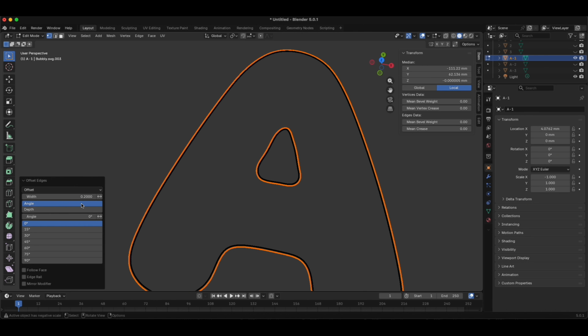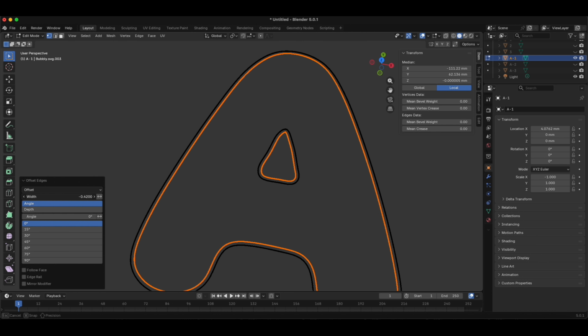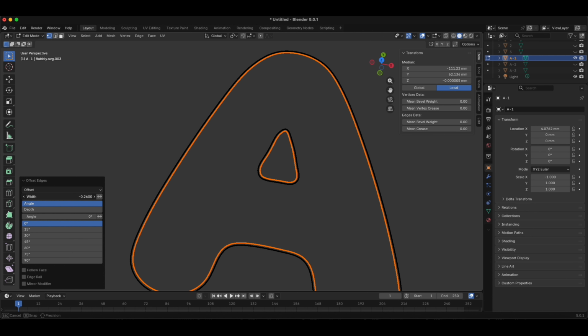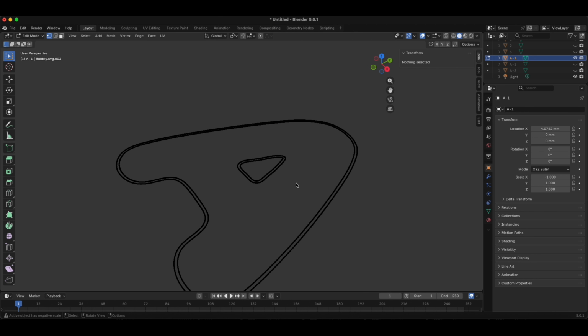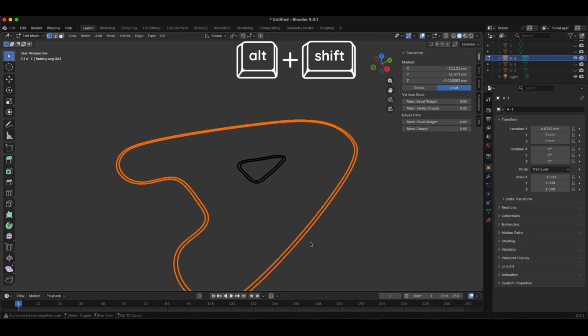Now we're making the outline, the offset for our blade. Our blade should be 0.4 millimeters, and this is completely enough. So here in this area, we go with our mouse down. We can enter it from the keyboard as well. Let's go not plus, but minus 0.4. This is our blade. And you just click wherever. Nice. Then Alt and Shift. I'm clicking this outline, holding Alt and Shift still, I'm clicking this one.